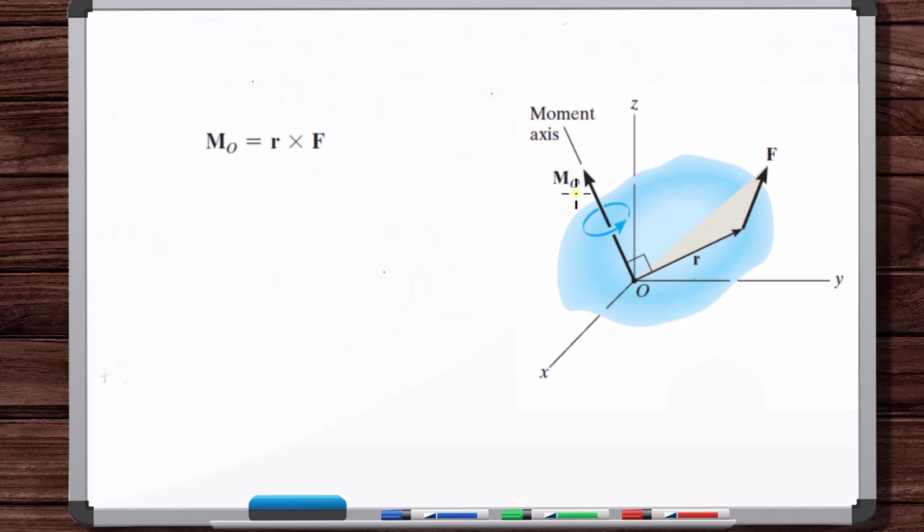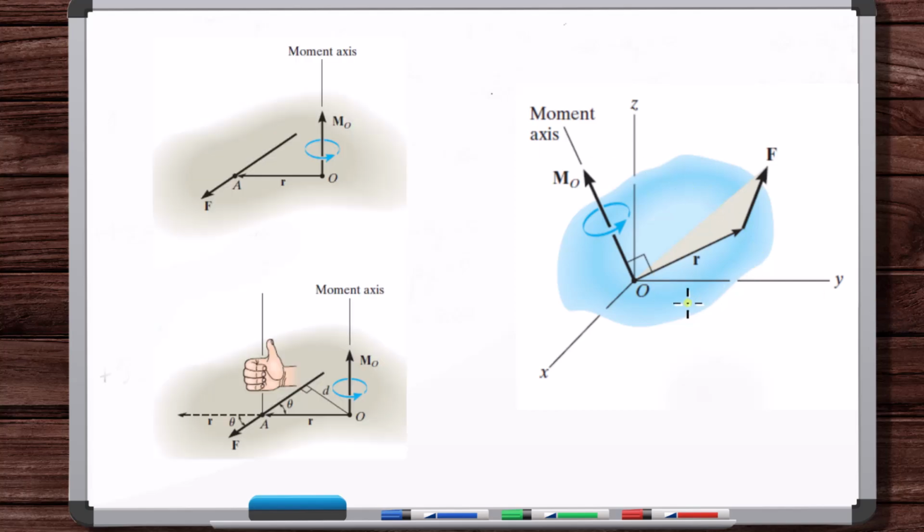Now, whenever you're calculating this, how do you know whether to put this vector here or here? Well, that's with the definition of the cross product. If you cross R with F, you could visually bring the tails of R and F together and then push with your right hand R to F, and your thumb is in the direction of the resulting vector. Or you can imagine visually sliding R up, and this is the angle between the vectors, and then you push R to F here.